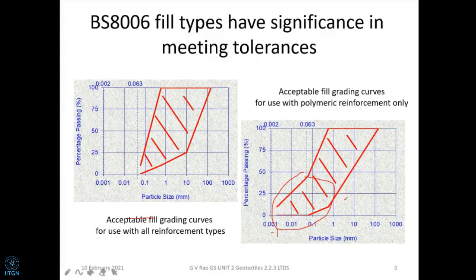By and large, in India, we use only granular soils for the fill material. We have no choice on the retained fill because that is natural soil, and also no choice on the foundation. Normally, if the soil is stiff and very good, we use the entire bearing capacity equation subject to factoring, and it is quite good because we have a large width. For a frictional soil, the width is a component of the bearing capacity, and because of that, very rarely is bearing capacity an issue.